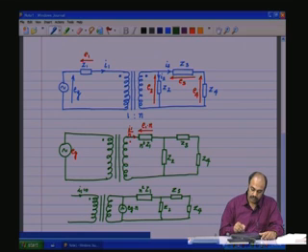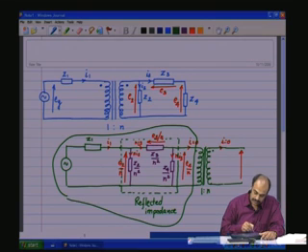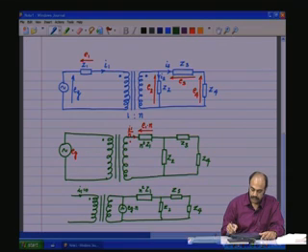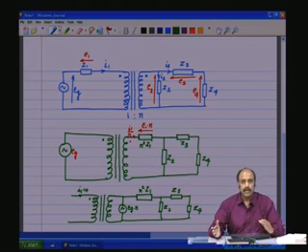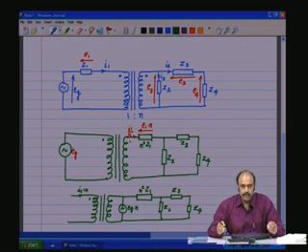This would be the equivalent circuit as seen on the secondary side, and we saw here the equivalent circuit as seen on the primary side. So, in this way one may choose to reflect the impedances either from the secondary to the primary or primary to the secondary for purpose of doing the analysis, depending upon the conveniences of the circuits.